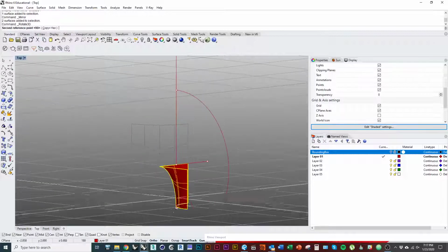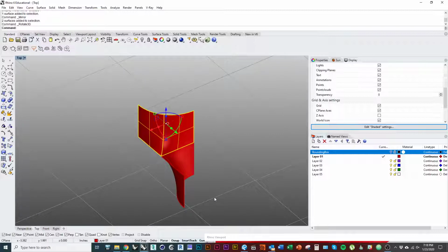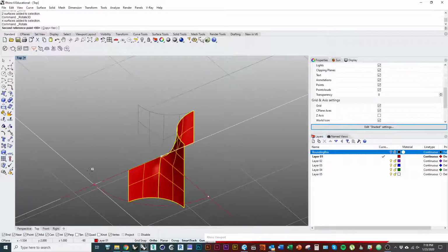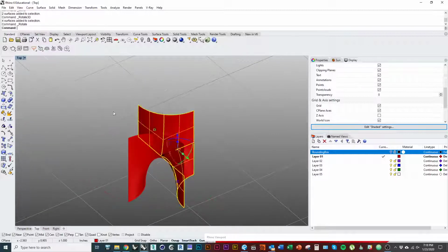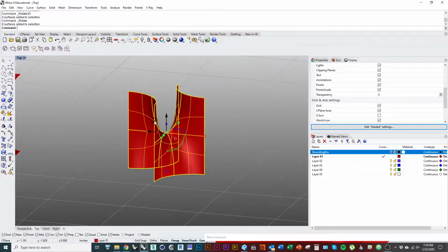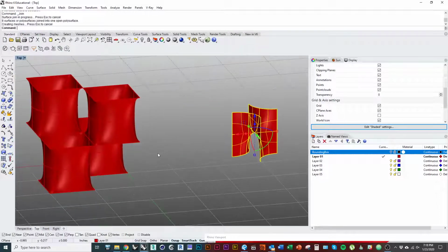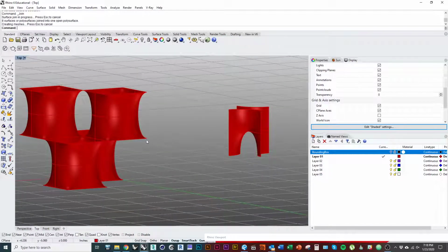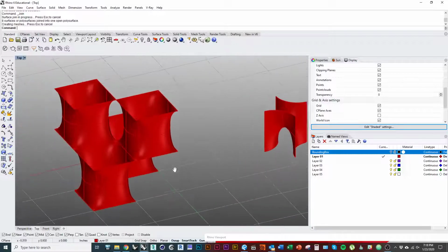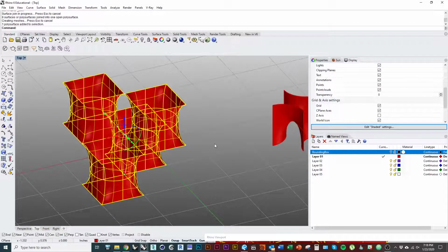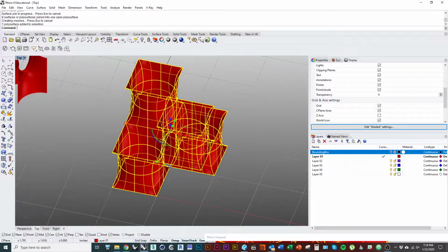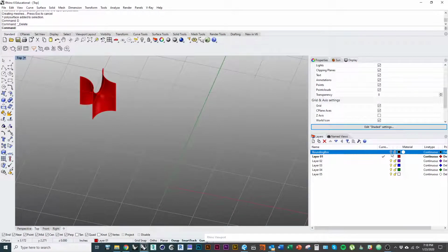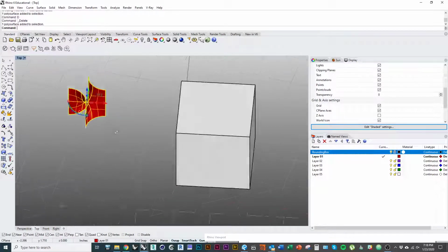And I think one thing to watch out for too, and you'll find this out when you start to model it, is how you think about printing. So for example, with this model, this is going to be difficult to print because there's an overhang right there. And this is a horizontal line that's just printing out in space. So when the printer gets to that location, it's just going to start printing on top of thin air, on top of nothing.